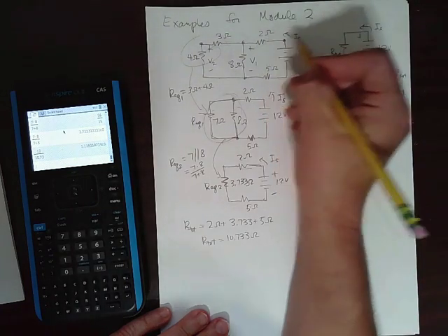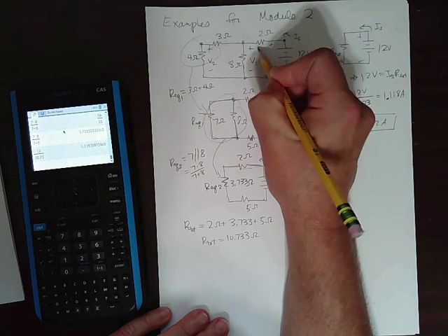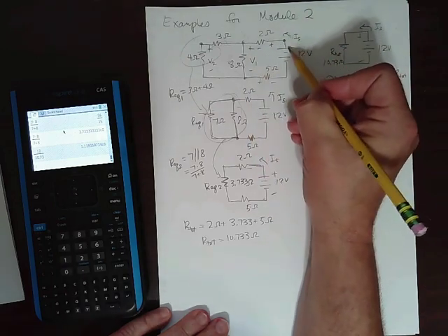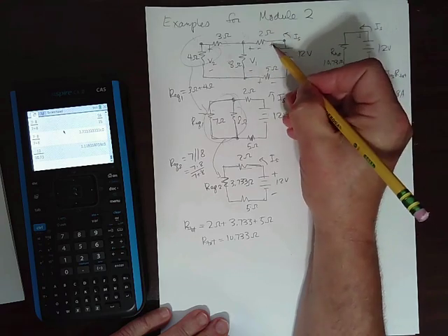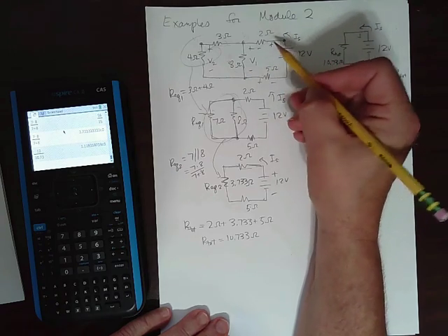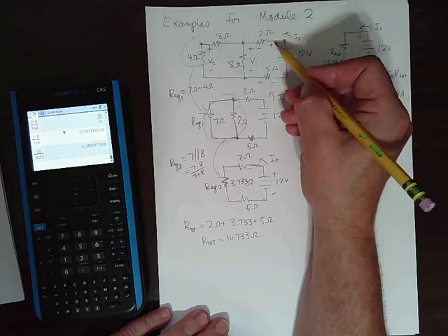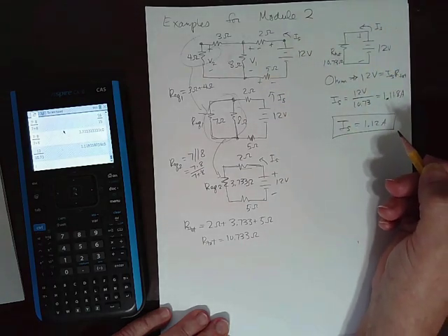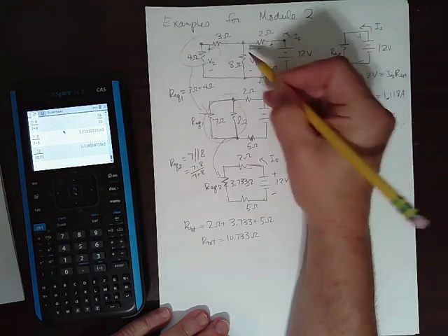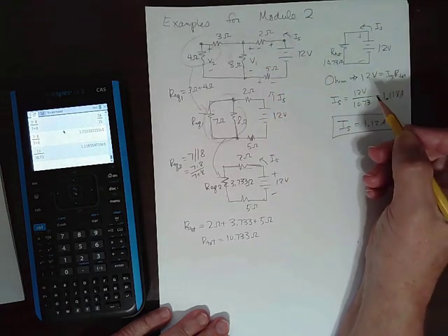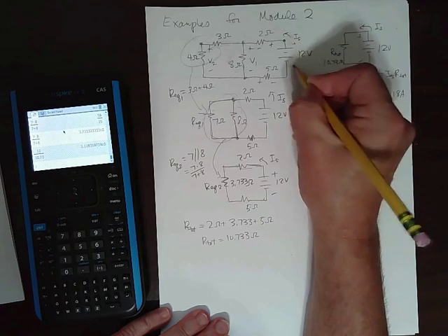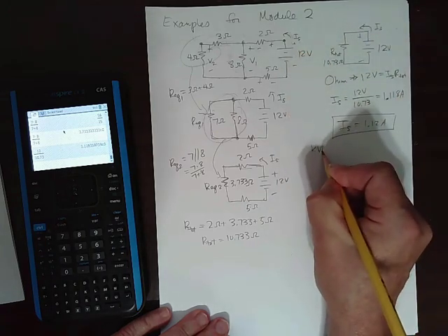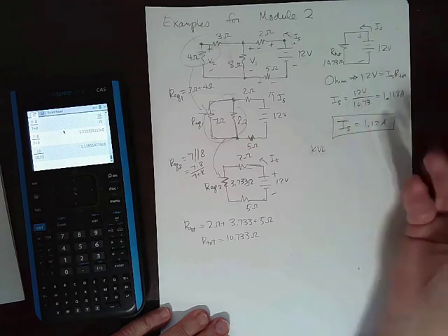Well, let's go ahead and name these voltages here. And I'm naming them with the current. So if you think of the current flowing around like this, I'm naming them so that resistors have positive sign convention when the current goes into their plus, right? And so we can write Ohm's law nicely for them. Okay, so let's go around the loop here. Let's just start here. Let's do KVL of the right loop.